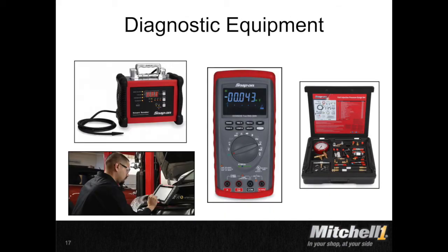And also, as part of this step to isolate the fault through testing, we also have our diagnostic equipment that we lean on to run those tests. So I just want to mention the oscilloscopes, which is really looking at voltage over time. This is also built in as part of your diagnostic tool if you have a Verus or Modus. We have multimeters, and what you're really doing there is measuring a voltage at a given point. You have smoke machines, and running a smoke test is a common thing to check for leaks. And also specialized equipment like fuel injection testing equipment to test the different specialized systems within the vehicle.